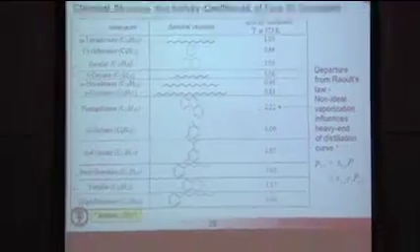Yeah? So then to go back into engine modeling, would you have to reduce that mechanism? So we keep all of these species because we're essentially just adding a few more species to the calculation. But then for the chemistry, what we'll do is group them and just say take all of the aromatics and treat them as though they had the properties of toluene in the reaction mechanism. Of course, when you do that, you add all the species of the toluene mechanism, so you're adding lots more species. So this list is relatively short compared to the chemistry.